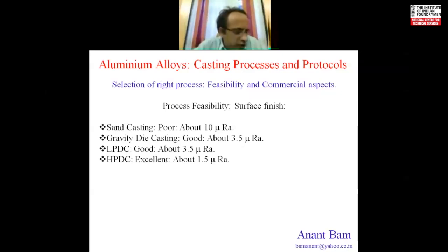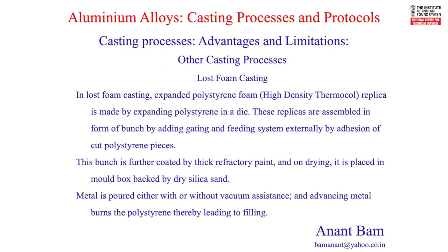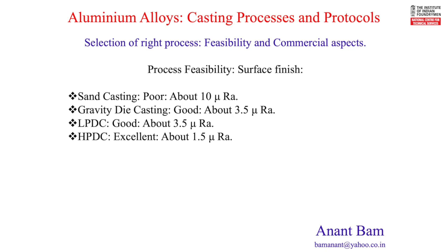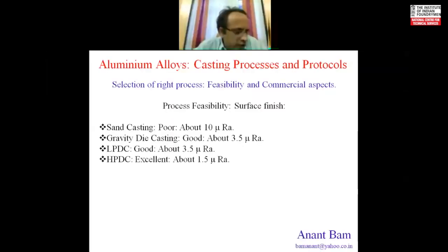Due to its liquid condition initially, this coating drips gravitationally downwards, thereby accumulating at any crevices or any horizontal place which it finds nearest. And such accumulation or lump formation leads to excess deposition of coating, thereby disturbing this finish. So any coating process has to be followed very, very carefully.